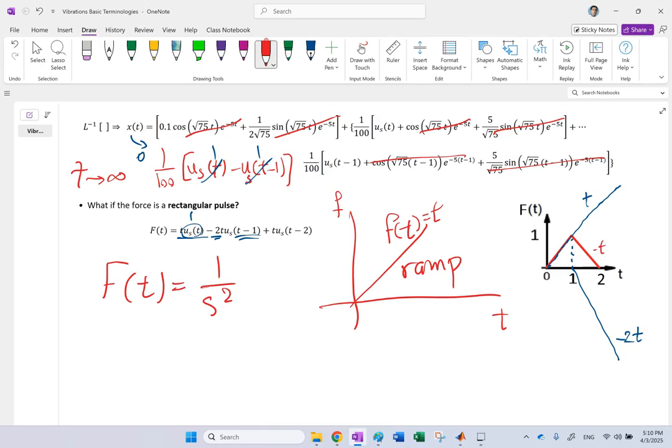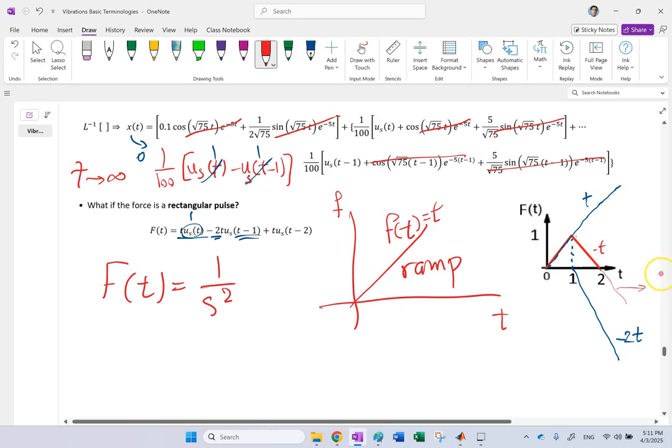Now, what happens when you combine these two? The problem is, for the time between 1 and 2, it does the job, it brings the signal down, but after t of 2 seconds from this point onward, what's going to happen? After this point, you have to bring the slope back to 0 because you don't want to continue this, you want to go back to 0. It's a pulse. So now what?